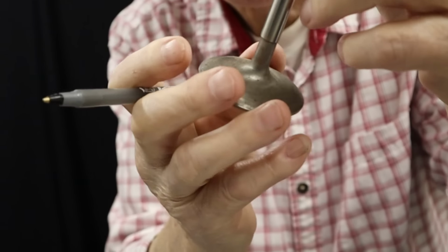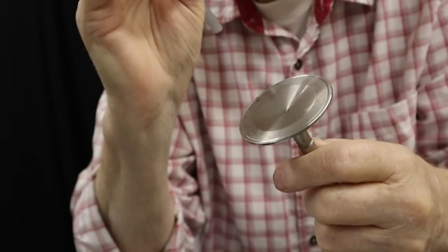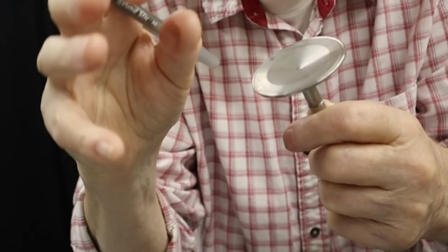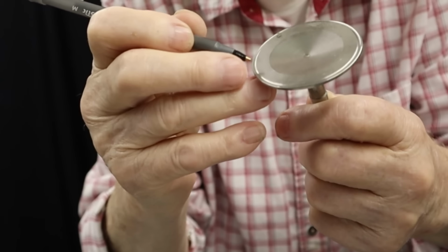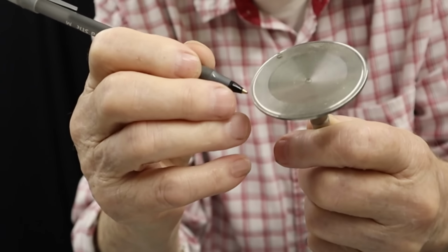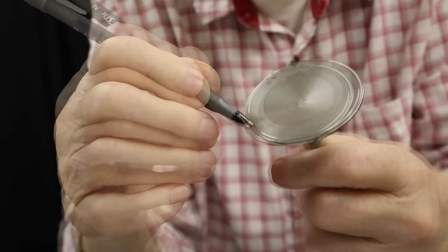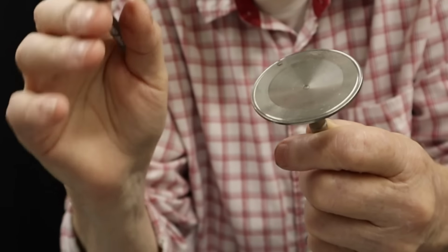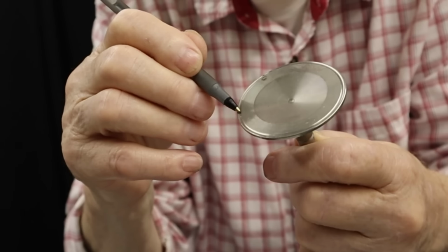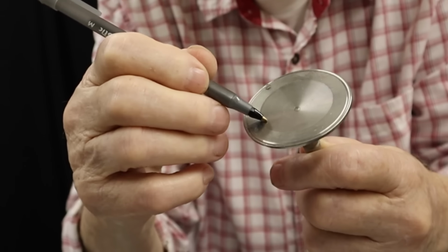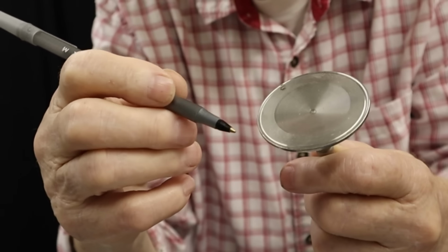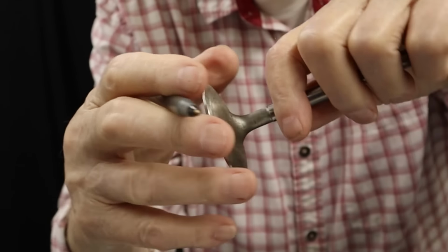However, once it's gone past the intake valve, then there comes a time where we run into the overlap period, and depending on how much the overlap is, there will be a tendency at lower RPM for the exhaust to want to flow out, because the piston could be coming up the bore at the end of the stroke and blowing out intake charge that had previously drawn in, because the port velocity at lower RPM is less. So if we make the exhaust valve have a poor discharge coefficient going out and a good one coming in, then we will have what I would call a secondary valving event.